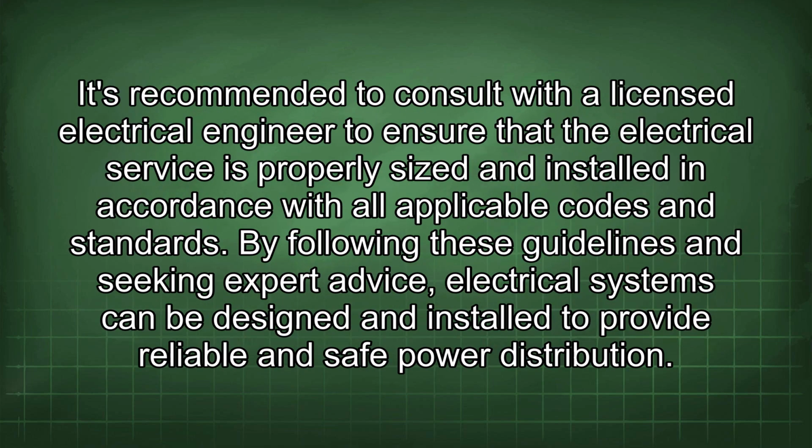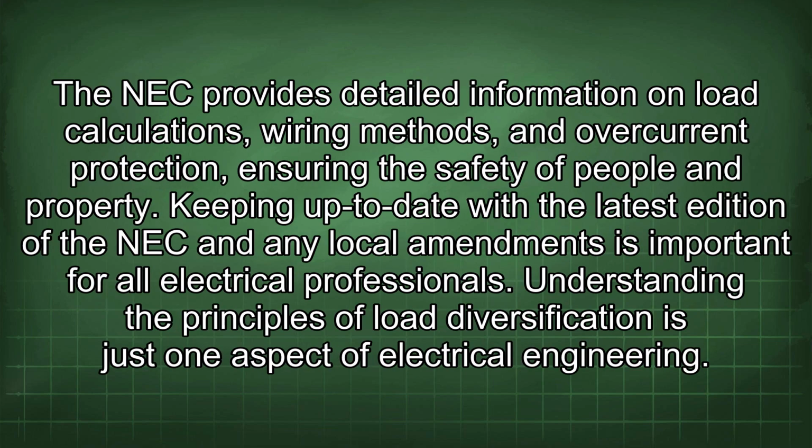It's recommended to consult with a licensed electrical engineer to ensure that the electrical service is properly sized and installed in accordance with all applicable codes and standards. By following these guidelines and seeking expert advice, electrical systems can be designed and installed to provide reliable and safe power distribution. The NEC provides detailed information on load calculations, wiring methods, and overcurrent protection, ensuring the safety of people and property.